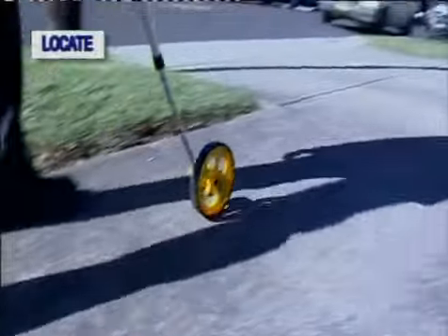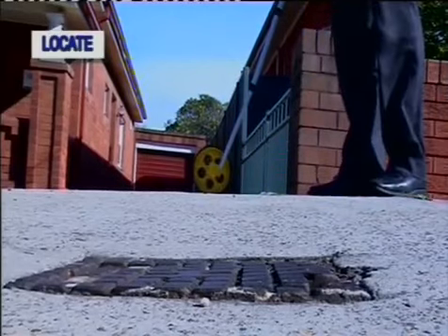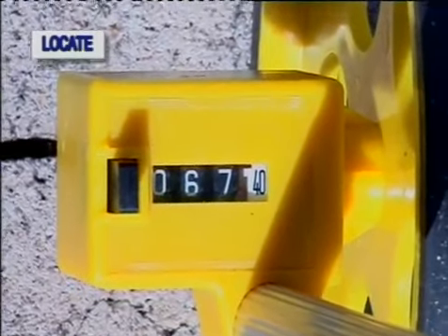So what we're going to do now is park between the 2 loggers on the corner of Duchess and First Street and communicate with the 2 loggers, downloading the sound recordings that were recorded to provide a correlation which indicates the location of the leak. This is a really high quality correlation, and I'm very confident there's a leak here. The peak indicates the position of the leak, and we can see that it's 30.5 meters from the hydrant on the corner of Duchess Avenue and First Avenue.